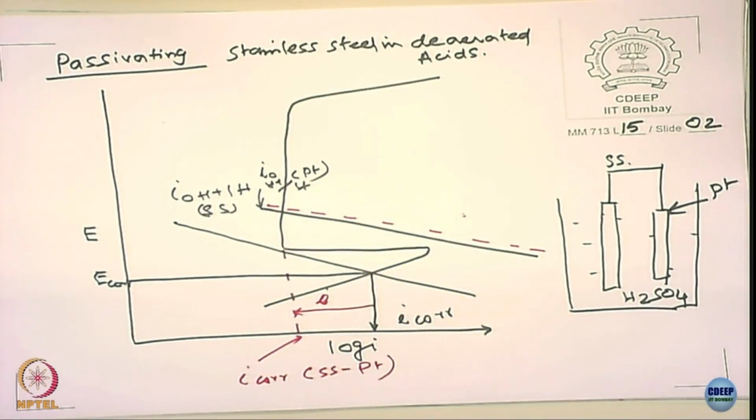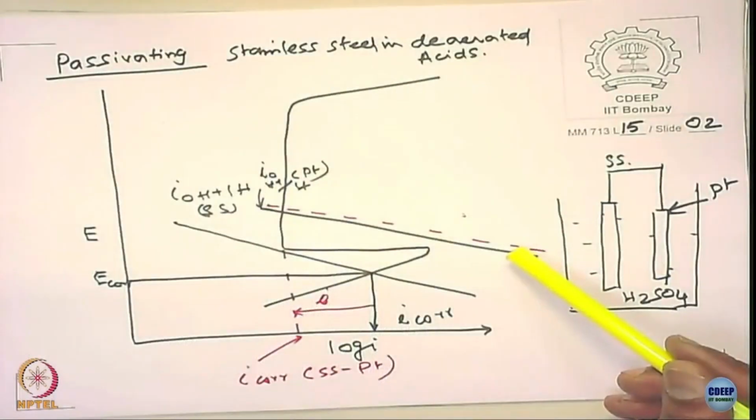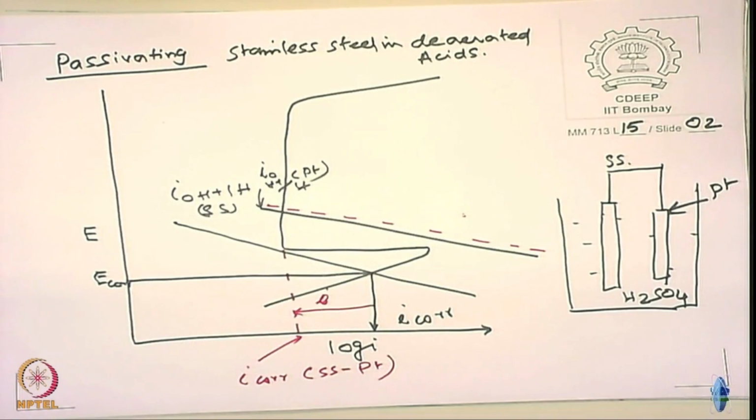Does it reflect something we discussed earlier? Is it cathodic protection? Is the potential moving cathodic? Huh? It's moving anodic, right? The potential is moving anodic, so it is similar to anodic protection. In anodic protection, you are applying an external current by a potentiostat. Here, you just use a platinum. The platinum can enable the passivation of the metals. Possible. I am not saying to do it, but it's possible that you can do.